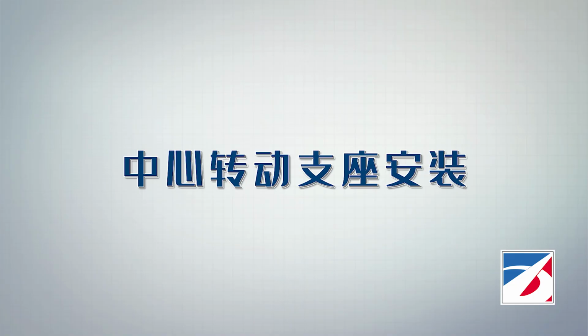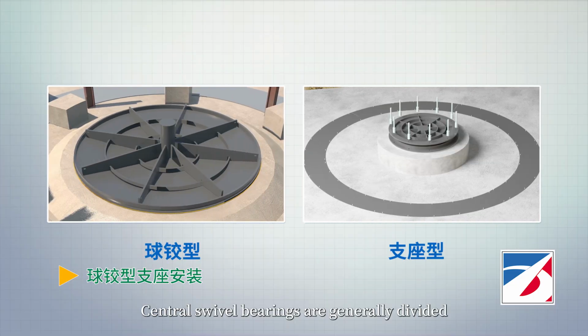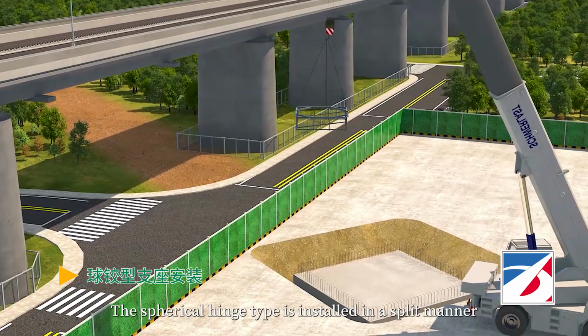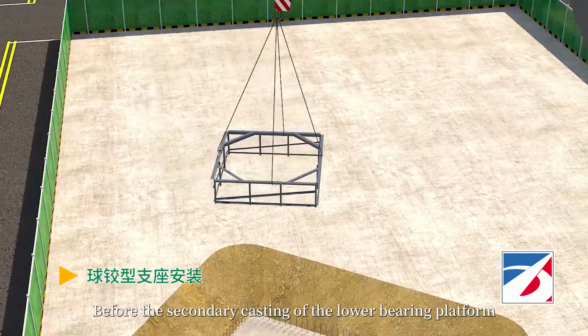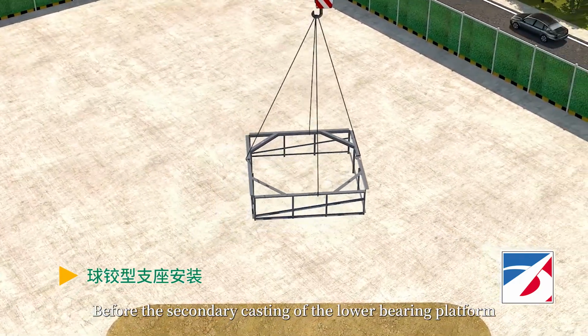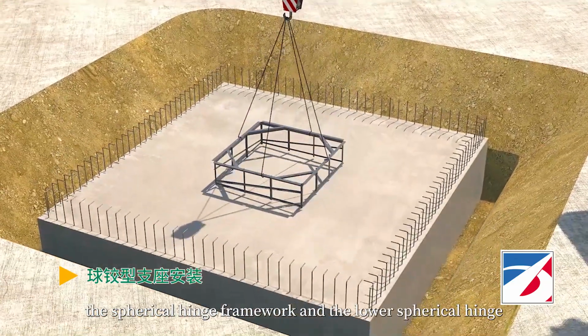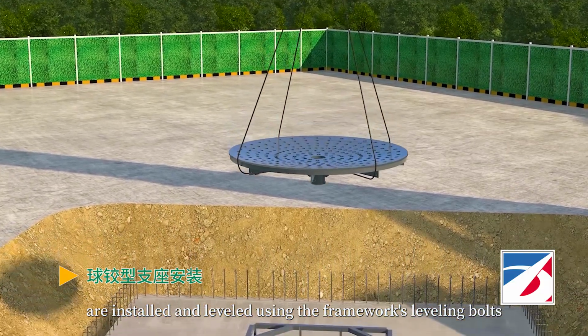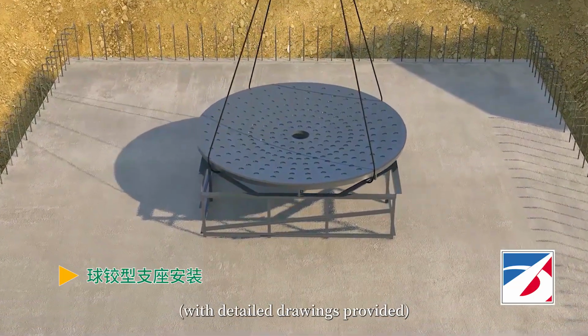Installation of the central swivel bearing. Central swivel bearings are generally divided into spherical hinge type and bearing type. The spherical hinge type is installed in a split manner. Before the secondary casting of the lower bearing platform, the spherical hinge framework and the lower spherical hinge are installed and leveled using the framework's leveling bolt, with detailed drawings provided.